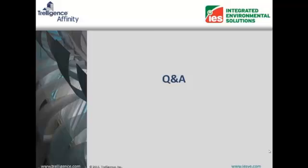And so part of it would be the first step where we're doing just schematic. We would go in through Affinity. We would use the basic settings. We would run an analysis and make changes. Then later, we would take the information. If we re-exported something from Affinity, we could then use model merge to say, I created some custom constructions inside of VE. I want them applied to my new model. So it's very quick to do. It's just, where are you creating the data? Where do you want to do it? How detailed are you getting with your analysis? And it's really, usually for architects, about the stage that you're at with the design.